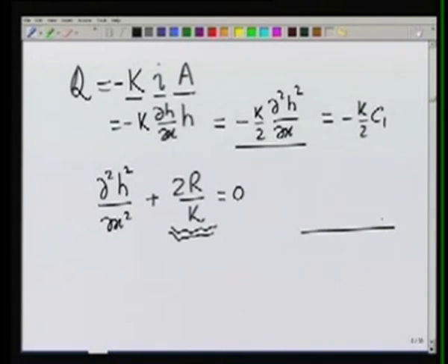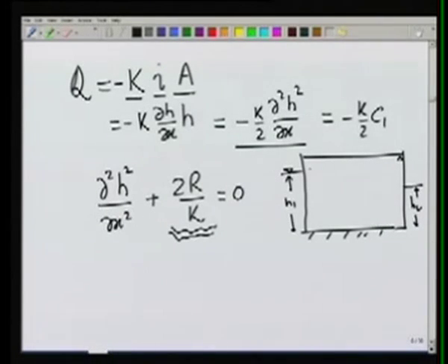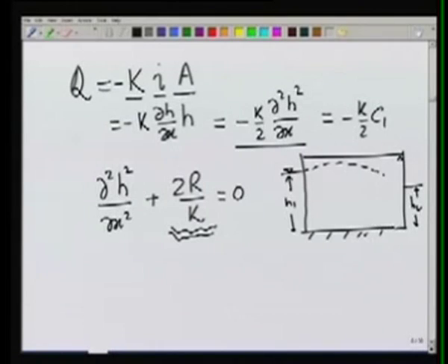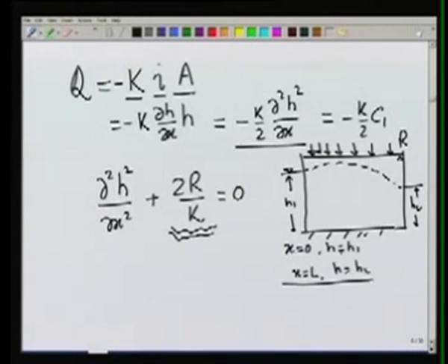will see that the groundwater table may rise above the level H1 because there is recharge coming in here at the rate of R. So because of this recharge, groundwater table may rise, and we can find out the equation of this line by solving this equation with the boundary condition which are same, x equal to 0, so using these two boundary conditions we can obtain the value of h.